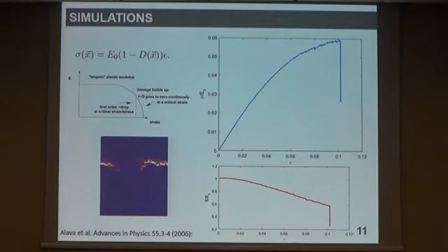If you take a look at the stress-strain response, you have this quasi-brittle behavior. It can be described by statistical fracture mechanics. You can find a nice review of it in this paper from Alava in 2006. Basically, the tangent elastic modulus decreases while the strain is applied and the damage builds, so you can see the stress as a function of the damage level of the material until a critical strain which leads to the failure of the material.